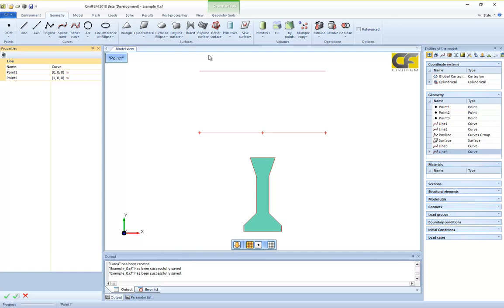If we want to create another type of geometry, which can be a volume, we can follow the same procedure. We have some already predefined primitives, which are cylinders, cones, spheres, or box volumes. By default, there are always some dimensions defined.